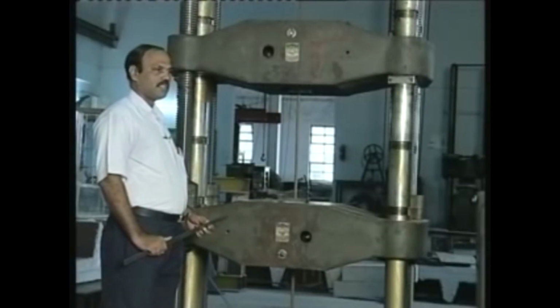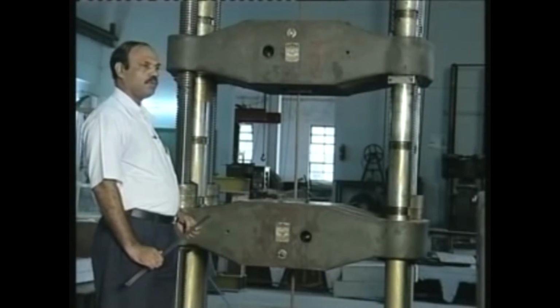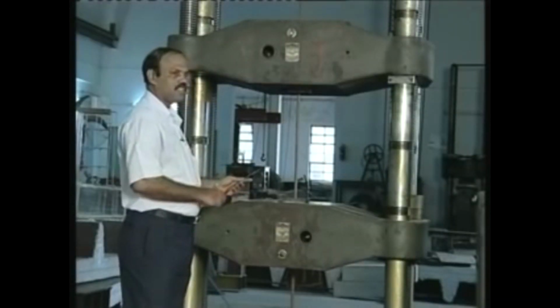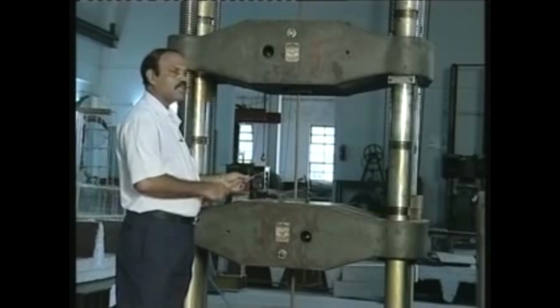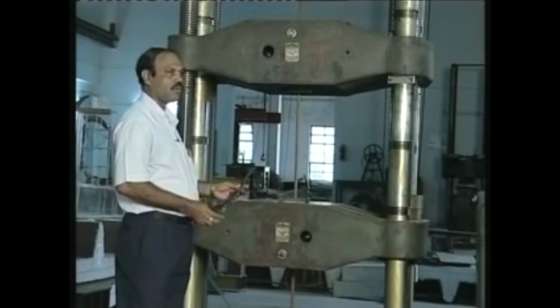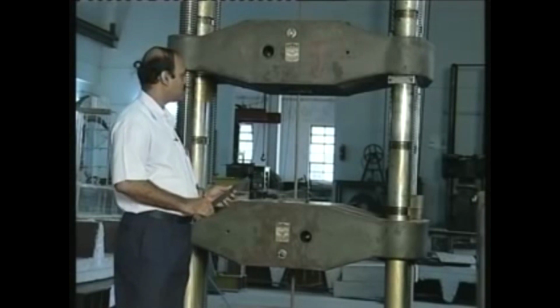The bar will be tested under constant axial pull, and the load will be applied till the member fails. The whole length of the bar has been divided into a number of segments, and each segment measures 40 millimeter. After the specimen is tested, after failure, we will remeasure the lengths and see how much extension these individual segments have undergone, which will give us the measure of the elongation that the material has undergone.